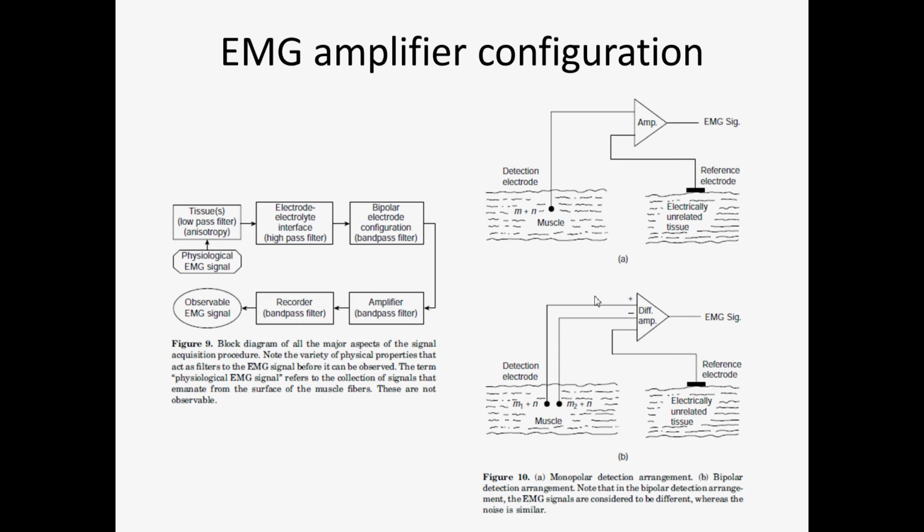So, volume conductor for EMG, well, it depends on what you want to observe. If you're doing some needle recording, you probably want to observe activity of the muscles, localize it. So that means you're going to take the difference between wires inside the needle referred to something else outside of the muscle.